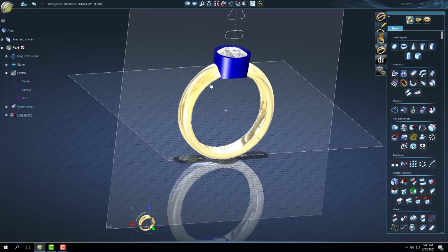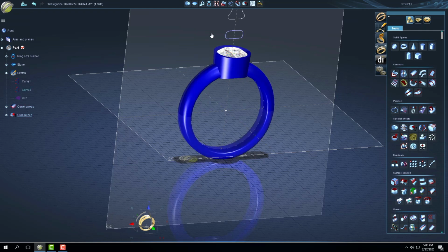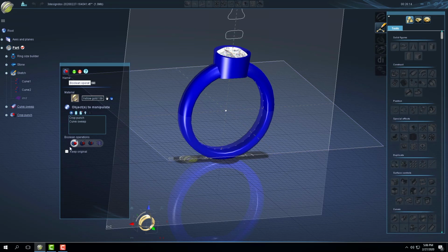So it's one piece. These are right now separate pieces. When we Boolean them, they'll be one piece. So this surface won't exist anymore. It'll just be from here to here. So anyway, let's select that. Boolean it. By default, it's on add, but there's also a subtract and a Boolean intersection. And I won't go into Booleans right now, but we're just going to add them together.